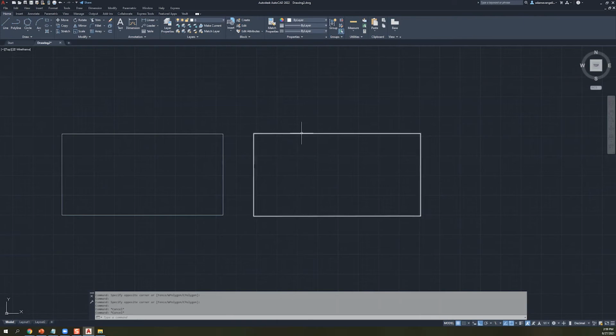If I choose the top edge of the polyline, I'm actually selecting the whole object, right? And that already gives you a hint about what polylines are. They're a continuous object, even if they're made of multiple line segments. And that's already an important distinction. Similar to before, that distinction ends up affecting various commands in the future, like hatching and stretching and stuff like that. A bunch of stuff may or may not go on, depending on what you're trying to do.